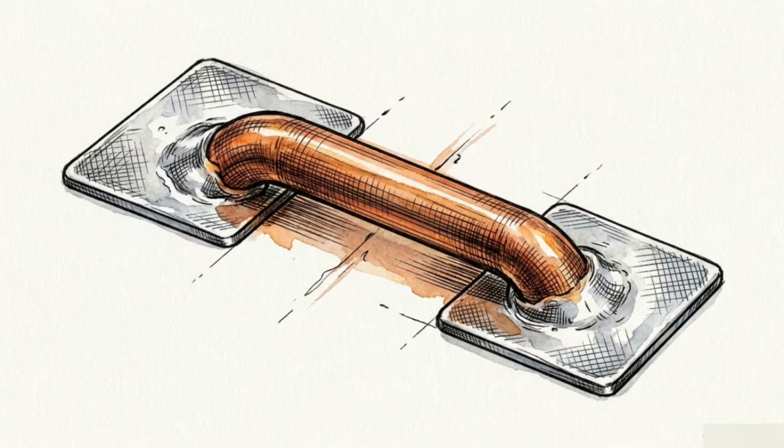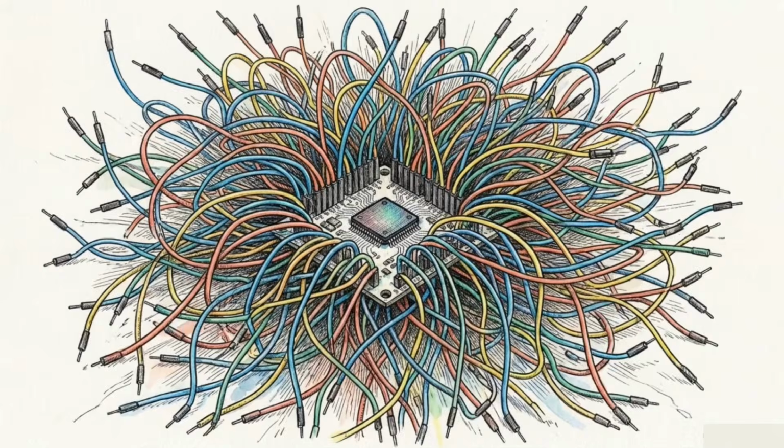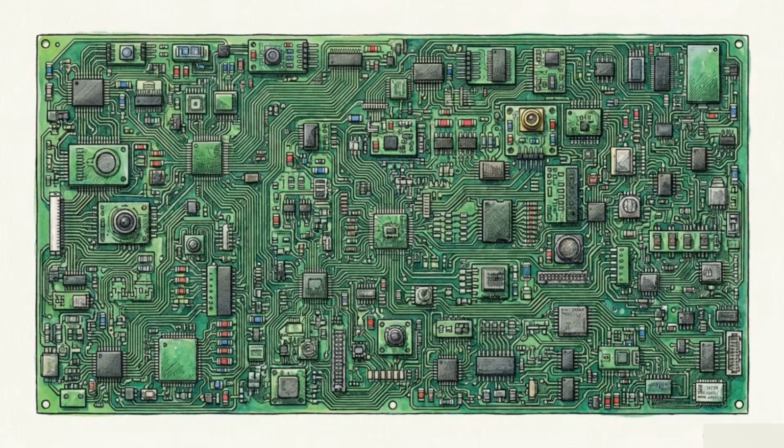UART works well for simple, direct connections, but dedicating 2 discrete I/O pins per device becomes physically impossible to wire when a single microcontroller must manage dozens of peripheral sensors. Routing a sprawling network of sensors using point-to-point connections requires an unsustainable amount of physical hardware on the main processor.